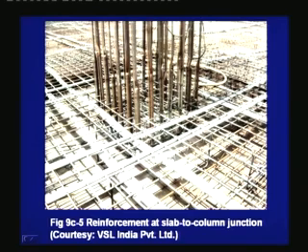This is a close-up view of the reinforcement around the slab to column junction, and you can see that the ducts have been spaced closely around the columns, and also the reinforcement is much higher around this slab to column junction, which helps to transfer the shear that generates in this junction.